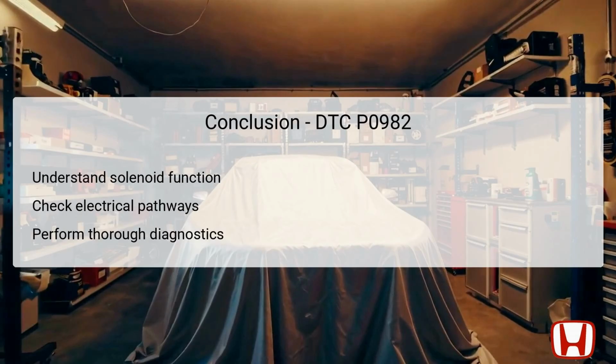In conclusion, addressing DTC P0982 requires a comprehensive understanding of the shift solenoid valve's function within the Honda CRV's transmission system. Emphasis has been placed on diagnosing and troubleshooting the underlying electrical issues rather than mechanical failures, underscoring the importance of thorough and methodical workflows.